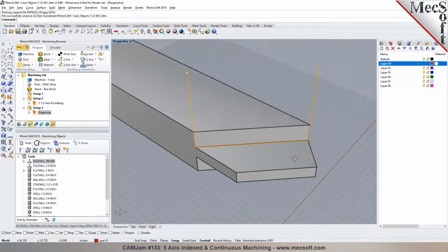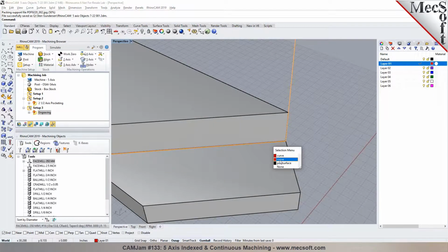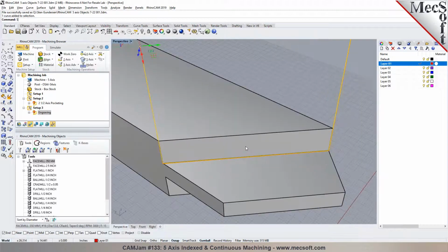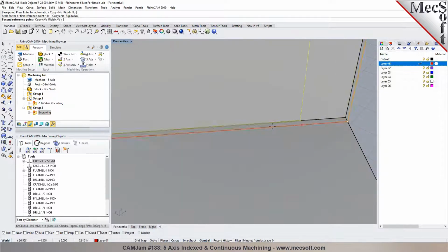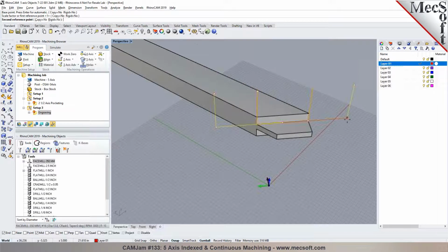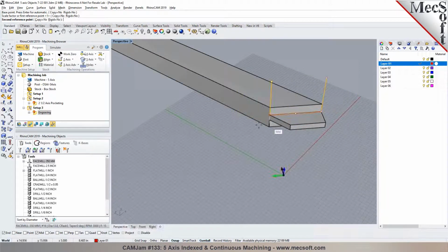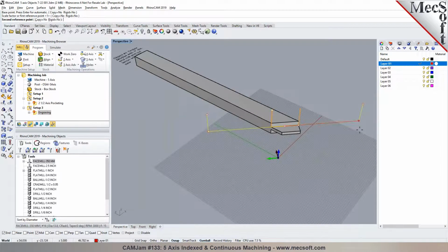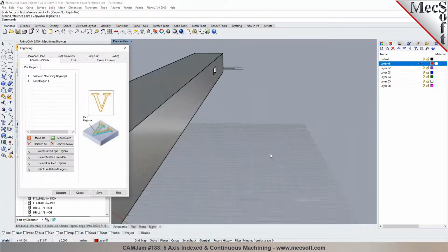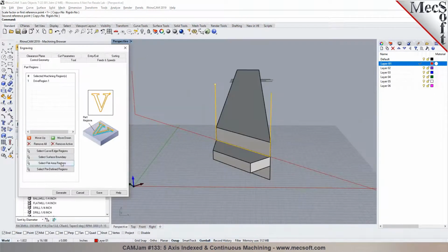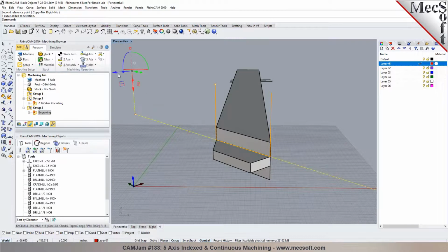And I'm going to extend this out also by the tool radius. So I'm going to pick this, and I'll do a scale, 1 dimension. I'll pick the midpoint of this line. Then I can extend it out on both sides, right? Yeah. That's perfect for the cutter to be well clear of the part, so I can pick how far I want to extend out. So now I can go back into this operation in here. I may have scaled the wrong one, but I'll go back and move this out by 1/16 of an inch.